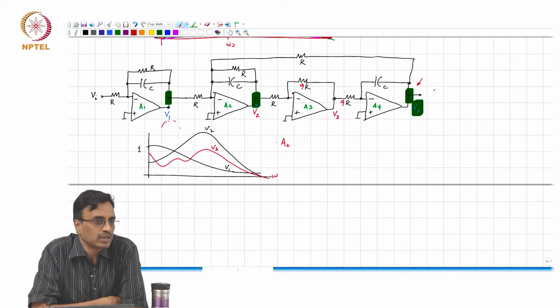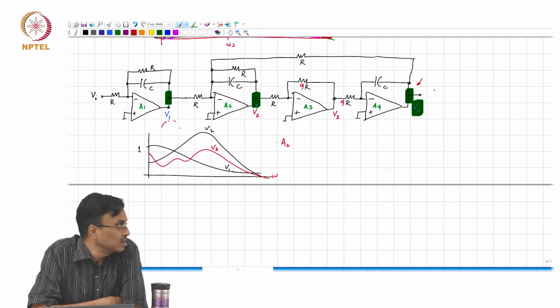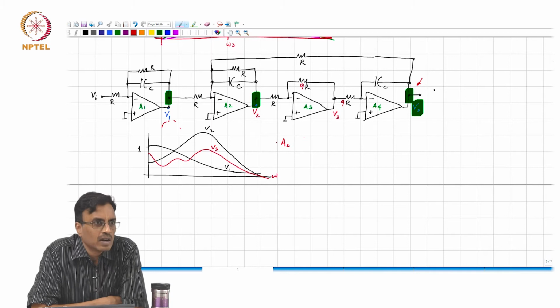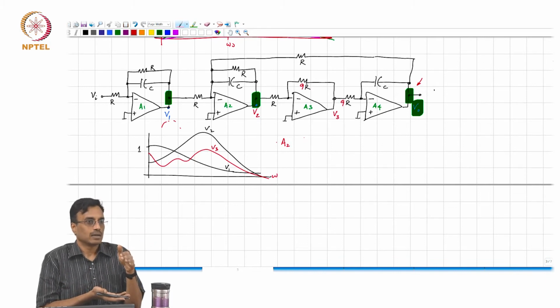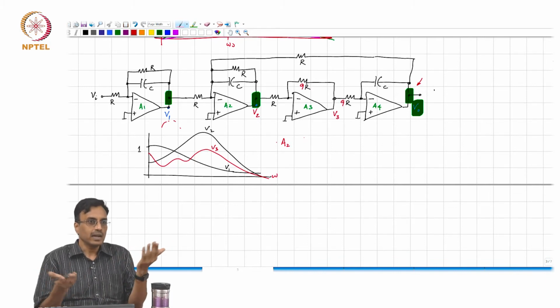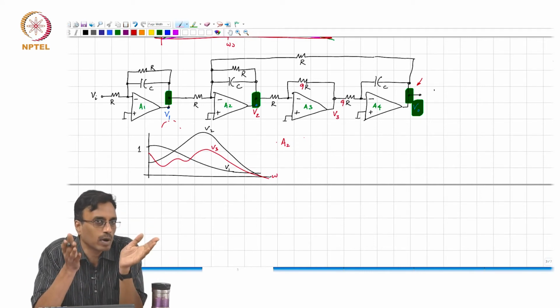No, that's how do we fix the problem, but what do we conclude first? So the conclusion is that A2 limits the maximum input you can put in, and it limits it to V sat by 22, right? And ideally, what is the maximum input you would like? V sat, correct? So what would you do? Therefore, how would we fix the problem?